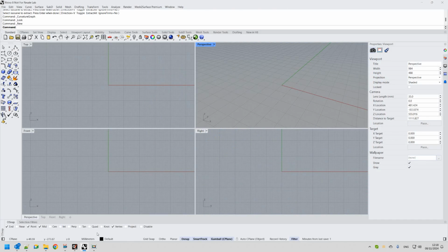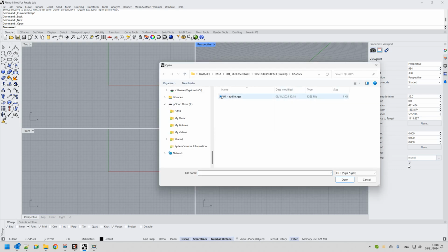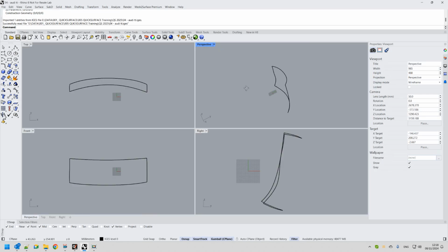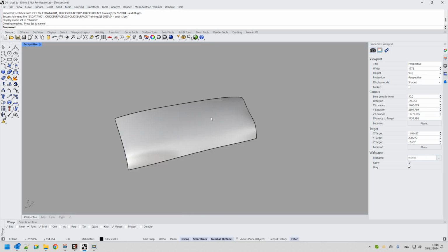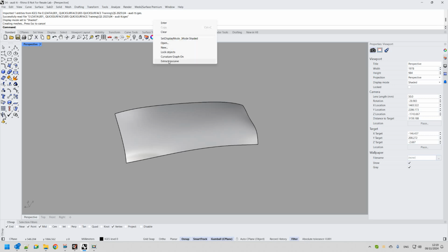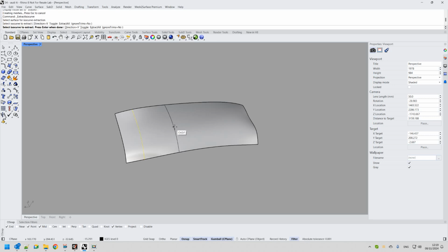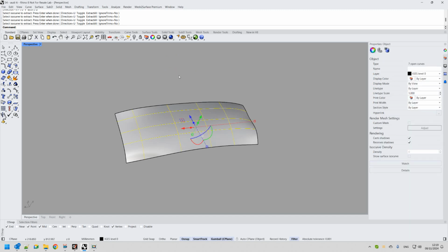And we'll bring it into Rhino. In Rhino, what we can do is extract what is called the isolines. Let's quickly do this just by extract iso curves, and we'll create several of them. We'll change the direction to the other way. It's actually something like this. What I'm going to do now is turn on the analysis of the curves.